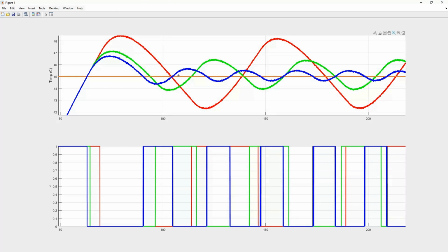Now, in these three situations, you can clearly see that all three of them eliminate the chattering. So you definitely want the blue. So you want to have a small deadband. Now, the flip side to that discussion is, is there a problem with having a small deadband? Well, the problem with the small deadband is, what if you have a really noisy system, right? If you have so much noise that the noise actually bumps you onto either far side of the deadband, then you now have a slight problem.